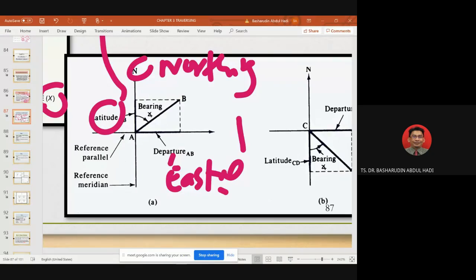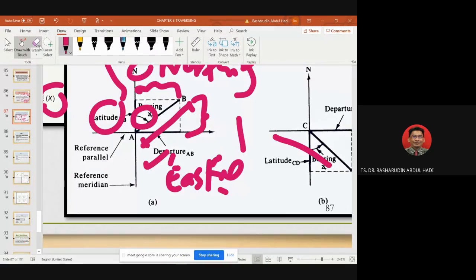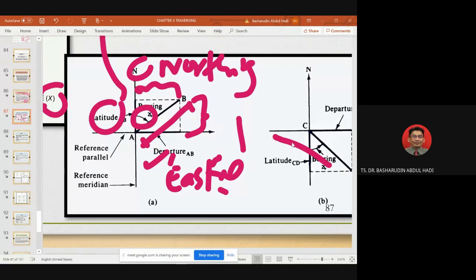Okay, all right. So here again, they will explain about the angles from north, and then again about this length. So from this angle and length, we can assume the latitude or northing, and we also can know this distance based on departure or easting. And there's another one. If you look at this one also, it's the same fundamental concept.